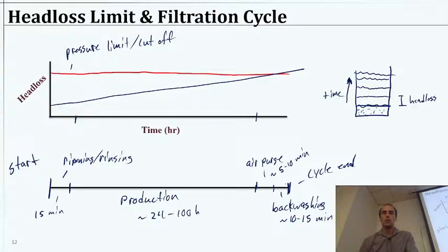And the water level is getting higher because it's having a harder time getting through the granular bed. Exactly. So the resistance caused by the particles getting stuck in the media makes it harder for water to pass through, meaning it's resisting that pressure, meaning the water level will rise accordingly.